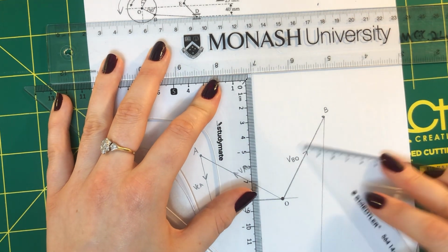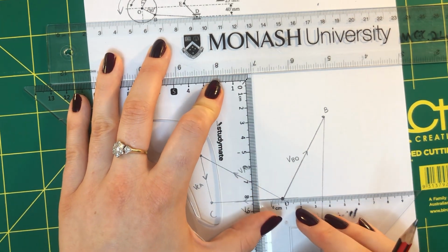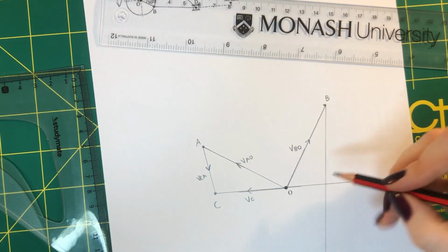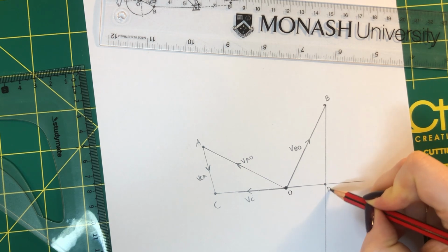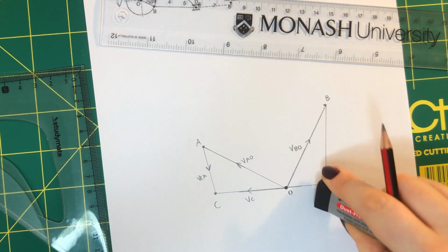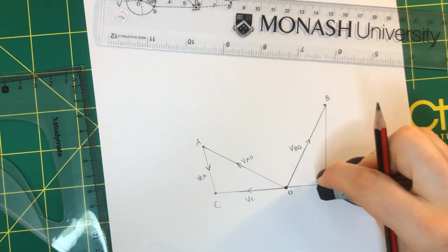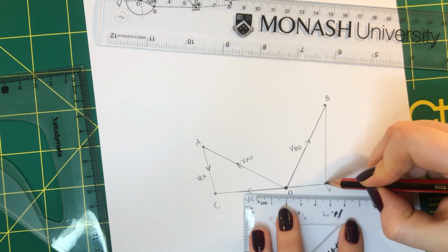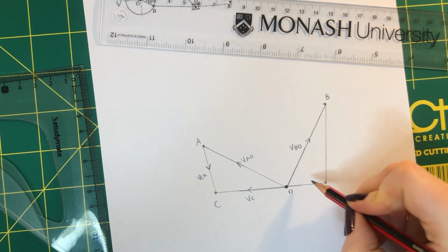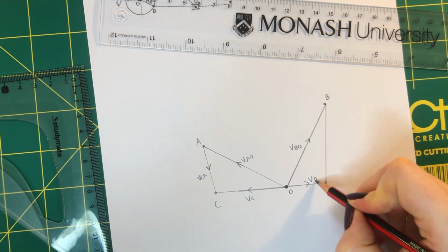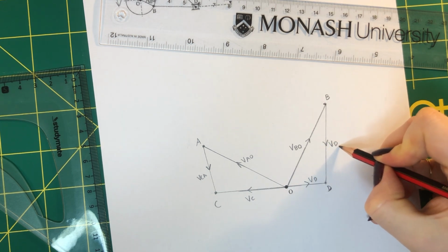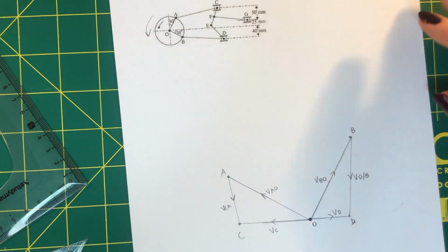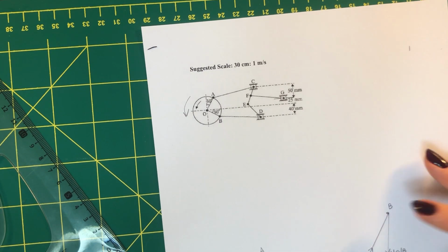And then the second set square. Really easy way of doing a parallel line. So where these cross, this is point D, and I'm removing my excess lines and remembering to label as I go. So I have the absolute velocity of D, and then I have velocity of D relative to B. So I have 4 lines now on my diagram. Let's have a look what's next.